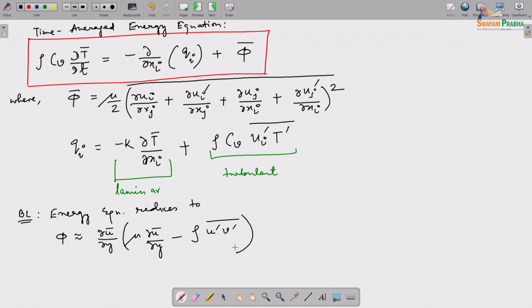What is different for a boundary layer? It is a little off question because we are specifically talking about turbulence here, but essentially what is happening in a boundary layer is that the velocity in the direction of flow, which is u, has fluctuation that is not trivial in the y direction, perpendicular to its flow.